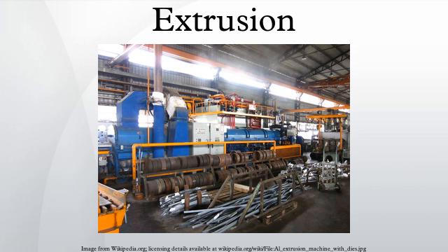A caterpillar haul-off is used to provide tension on the extrusion line, which is essential for overall quality of the extrudate. The caterpillar haul-off must provide a consistent pull. Otherwise, variation in cut lengths or distorted product will result. In some cases the extrudate is pulled through a very long die, in a process called pultrusion. A multitude of polymers are used in the production of plastic tubing, pipes, rods, rails, seals, and sheets or films.